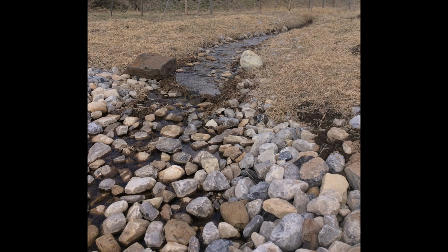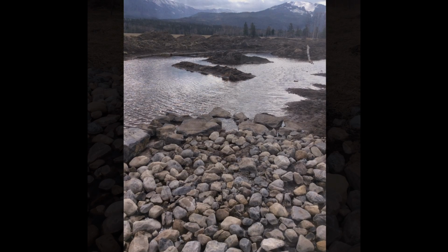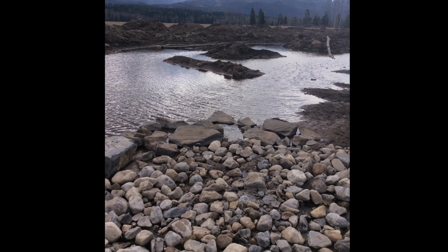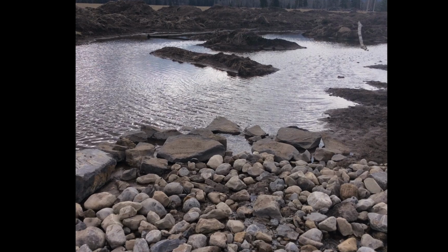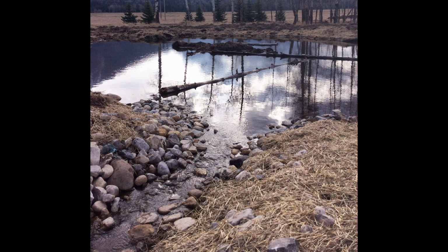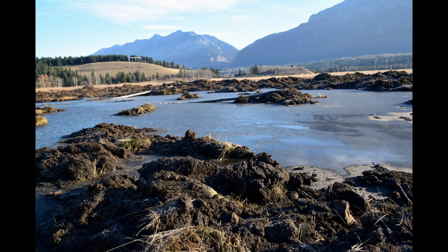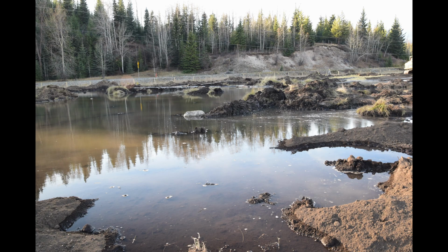To combat this problem, we moved the excavator around to where the erosion was occurring. We added more rock, pushing this rock into the ground within the spillways by using the excavator. We also used rock to armor the inlets where water from the ditch entered each wetland to control the erosion. The rock we embedded in the ground where the water flowed into the wetlands prevented head cuts from forming in the highly erodible soil. Here's how one of the wetlands appeared the day we finished the project. The wetlands quickly filled with water.